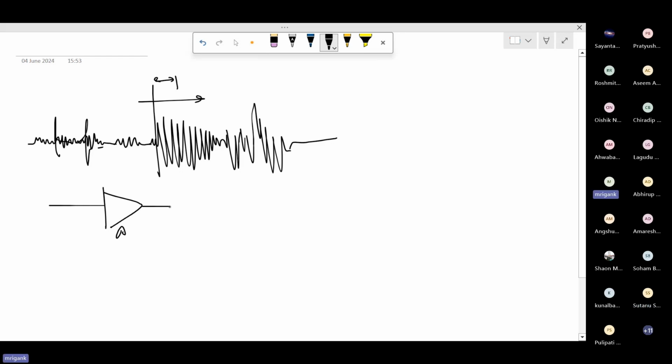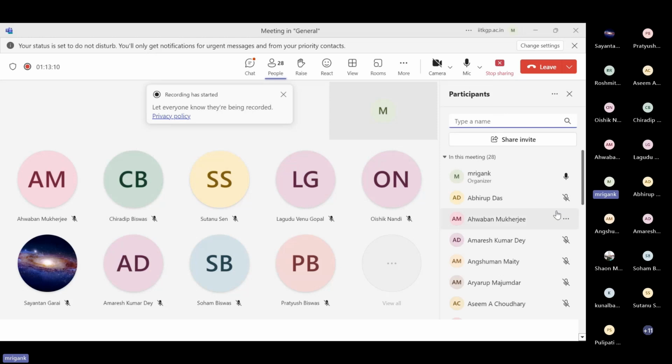What else? Then for noise, you can do sizing. So the noise can be taken care of to a certain extent by proper sizing. I have given you some recordings in which the noise analysis of single-ended as well as differential amplifiers was discussed, right? All of you have seen that lecture where the noise analysis is given, how the sizing of the devices, bias current of the devices, etc., affect the input referred noise. This entire concept of input referred noise. How many of you have gone through that?